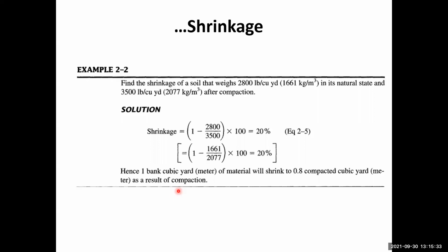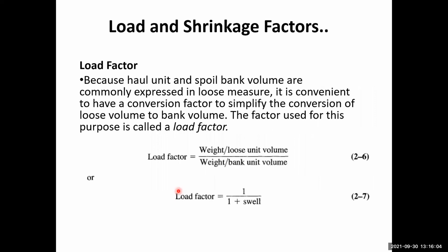Remember that swell is compared with the bank volume, and shrinkage is also compared with the bank volume. We are not comparing the loose volume and the compacted volume. The comparison is always with respect to the bank volume. This is how these two formulas work for the swell and shrinkage.